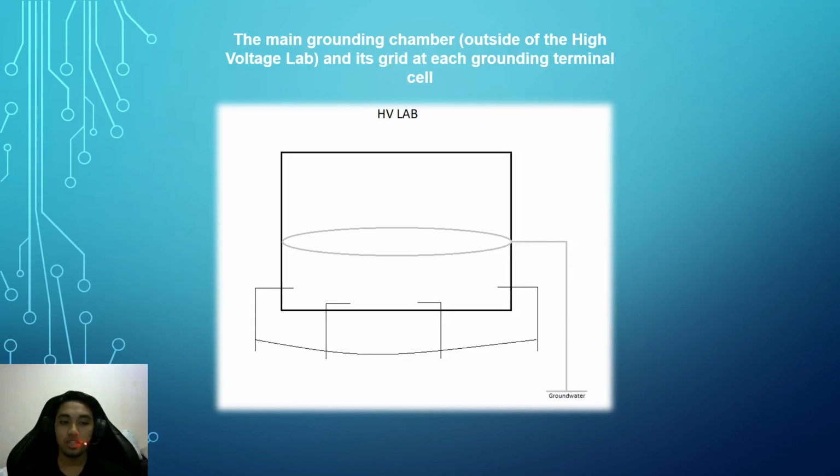According to the kit, to avoid ground loop between different grounding points, the kit is grounded at only one position to a ground rod. The rod must have ground resistance of less than 2 ohm. Hence, all of the instruments will connect to a special grounding.